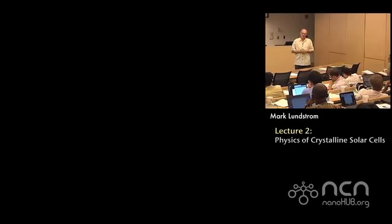So there are a lot of people doing research on whether graphene could make a transparent top conductor for solar cells. It's not a slam dunk. One layer of graphene doesn't have a low enough sheet resistance for solar cell applications, so you have to put multiple layers in. When you put multiple layers in, you get a little bit more absorption. But there's some promise of doing something there.